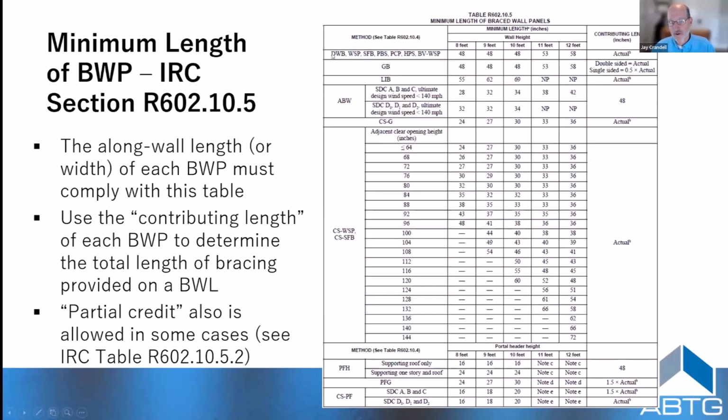So, if your diagonal wood board or wood structural panel or structural fiberboard or particleboard sheathing, or your Portland cement, you can use Portland cement. It's one of the strongest bracing methods in the code. The old-fashioned 3-coat Portland cement.